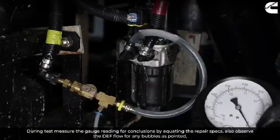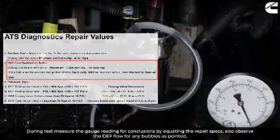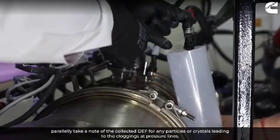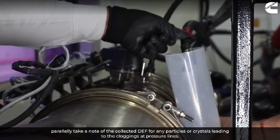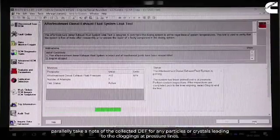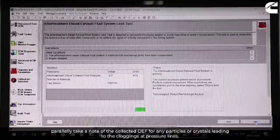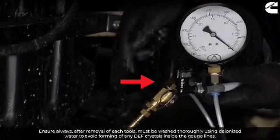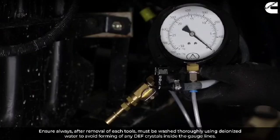During the test, measure the gauge reading for conclusions by equating it with the repair specs. Also observe the DEF flow for any bubbles, as pointed. Parallelly take a note of the collected DEF for any particles or crystals leading to cloggings at pressure lines. Ensure always, after removal of each tool, it must be washed thoroughly using deionized water, to avoid forming of any DEF crystals inside the gauge lines.